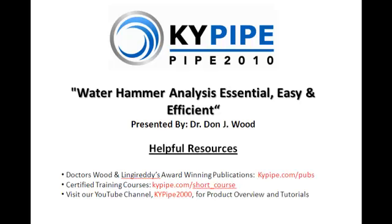Do pressure sewer systems typically exhibit pressure surge? Oh yeah, especially since so many of them have pumps that go on and off frequently, and there are a lot of problems that can occur if you're not looking at the surge. Surge is created when the pumps come on and off.